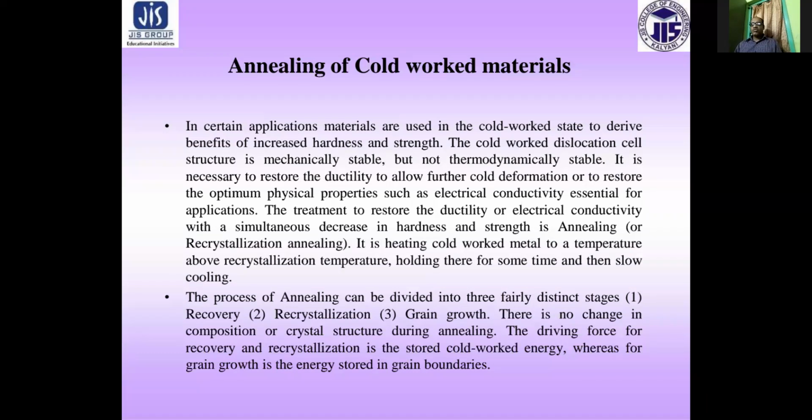It heats the cold work material to a temperature above the recrystallization temperature, holding there for some time and then slow cooling. It is divided into three distinct stages: recovery, recrystallization and grain growth. There is no change in composition or crystal structure during annealing. The driving force for recovery and recrystallization is the stored cold work energy, whereas for grain growth it is the energy stored in grain boundaries.